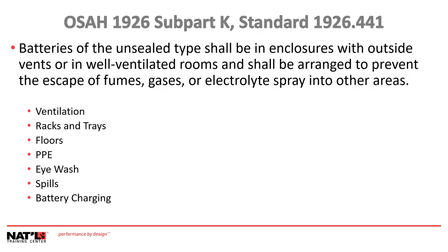Battery charging installations shall be in areas designed for that purpose, and the charging apparatus shall be protected from damage. When batteries are being charged, the vent caps shall be kept in place to avoid electrolyte spray. Vent caps shall be maintained in functioning condition. Let me help with why this is important for you to know and understand this. If you are doing acceptance testing and commissioning, you must ensure that all of these conditions are met. And if not, you need to annotate this and note it so that the owner or the construction company can deal with the issue.